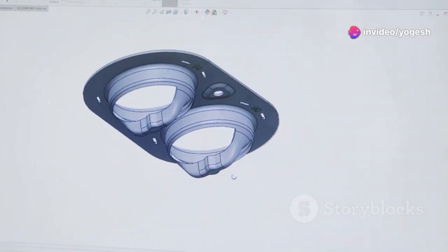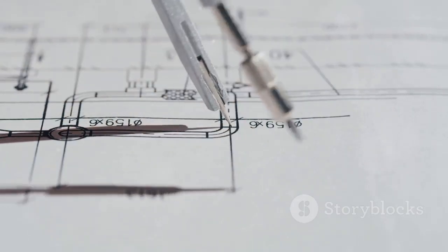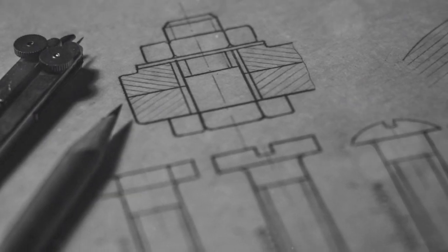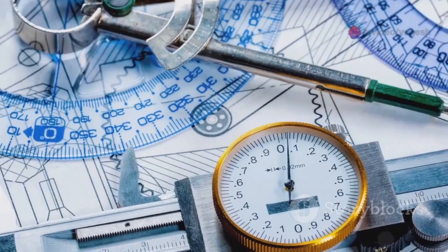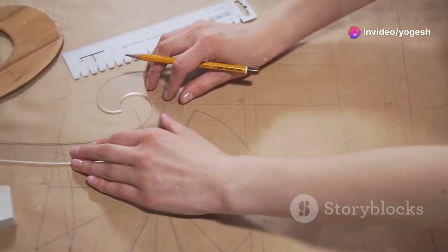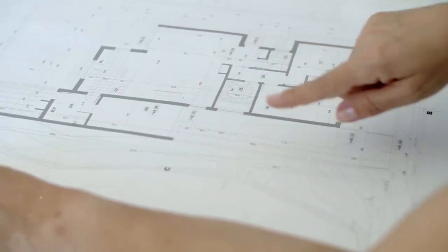Creating a great sectional view is only half the battle. Dimension it properly for clarity. Place dimensions where features are most visible. Avoid dimensioning to hidden lines. Keep drawings uncluttered and strategic. Use center lines for symmetry and dimensioning. Break hatch lines around dimension numbers for readability.